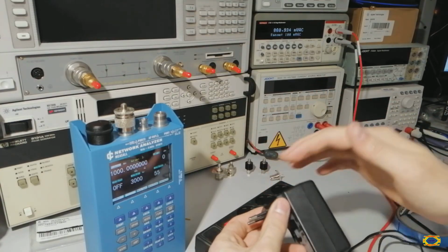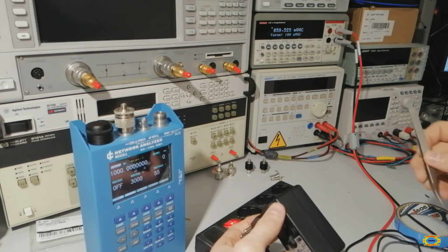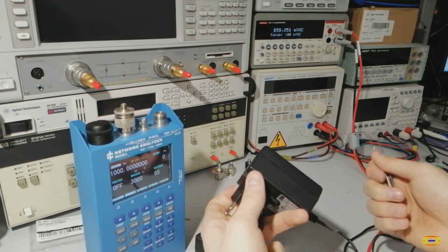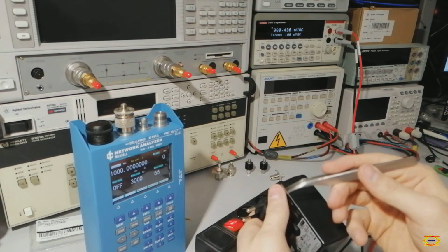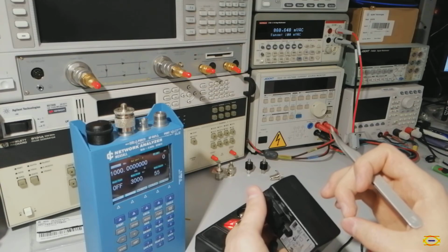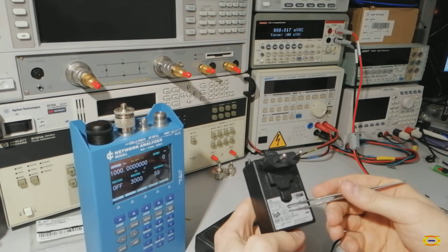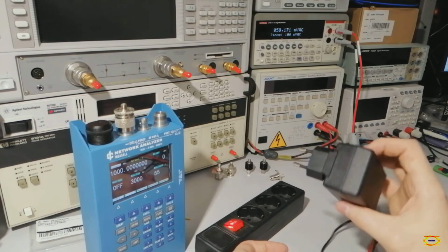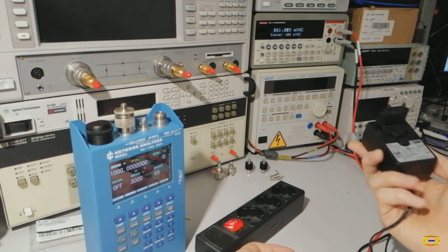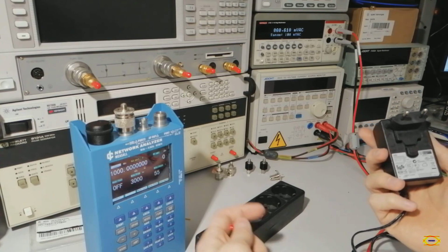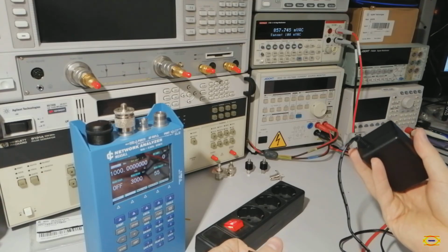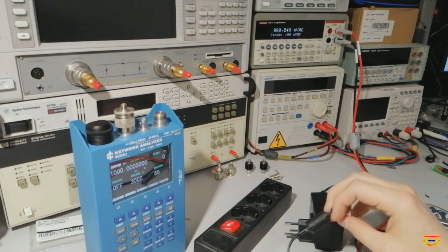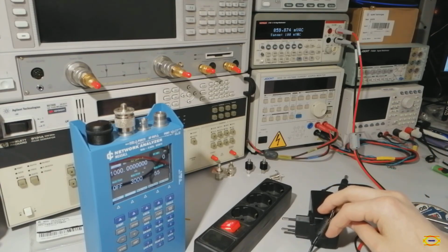AC voltage leakage from the input to the output is understandable, because you have some capacitors between the high voltage side and the lower voltage side, just for keeping the AC loop for noise closed. It's all done only for certification purposes, and of course you can pass certifications and get safety marks, but it's fully unsafe for your instruments. So yeah, we actually can't use that anymore, because if you're working with that charger, you should be very careful.